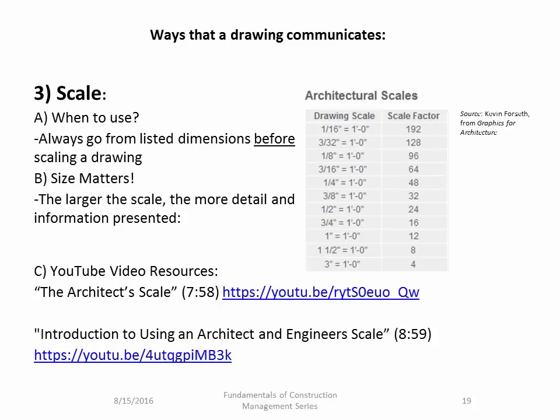But at the same time, size does matter. The larger the scale, the more detail and information that you're going to have on the page. On this slide, the architectural scales to the right that are grayed, if you go to the very bottom, that would be the largest scale that we have in this table. That is 3 inches to 1 foot. And the way you think about the scale factor there, which is 4, is if you had 12 inches to 1 foot and then you were reducing that scale down to 3 inches equals 1 foot.